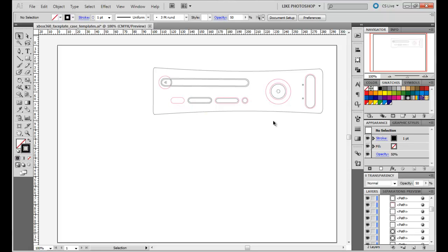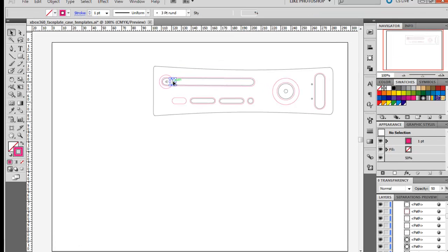The faceplate of the Xbox contains closed paths, which are disconnected from the primary body of the faceplate, but should still be printed. They will not be defined using a magenta color. I will define their boundaries like the perimeter of the Xbox is defined with the black color.